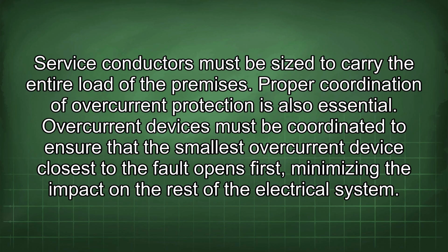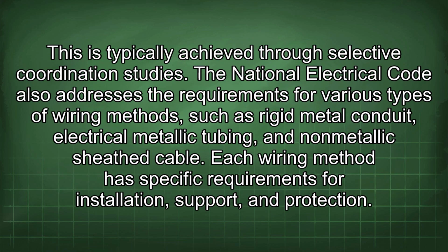Proper coordination of overcurrent protection is also essential. Overcurrent devices must be coordinated to ensure that the smallest overcurrent device closest to the fault opens first, minimizing the impact on the rest of the electrical system. This is typically achieved through selective coordination studies.